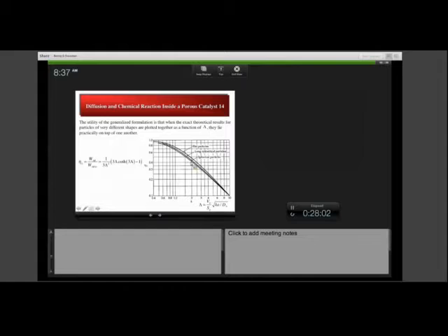The effectiveness factor is less than 1, and it tells you how much less the total conversion is than what it would be if you could expose all of the catalyst to that same concentration. And so I can write for these non-spherical particles, the effectiveness factor is shown here, and the Thiele modulus gets modified by the surface to volume ratio of the catalyst particles.